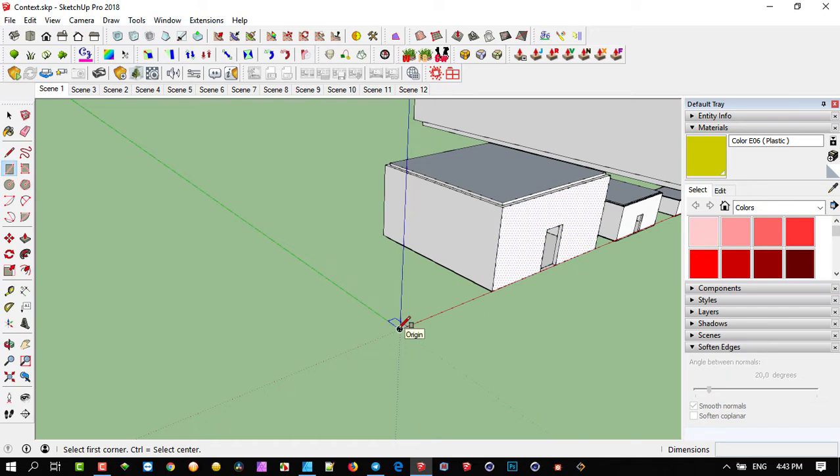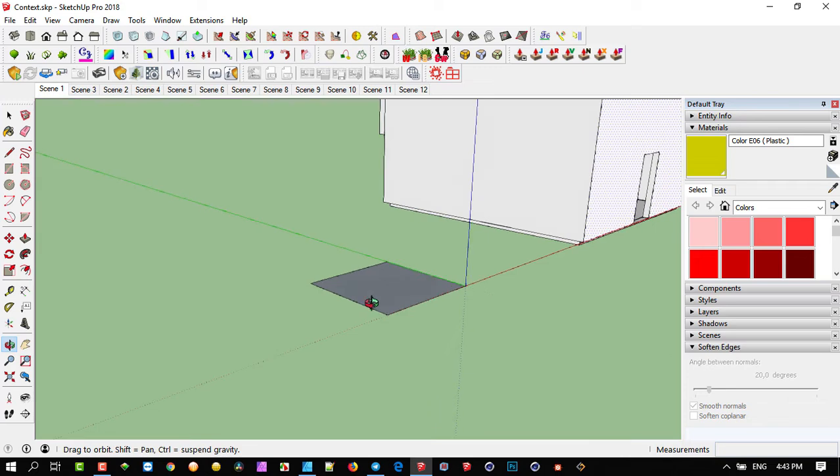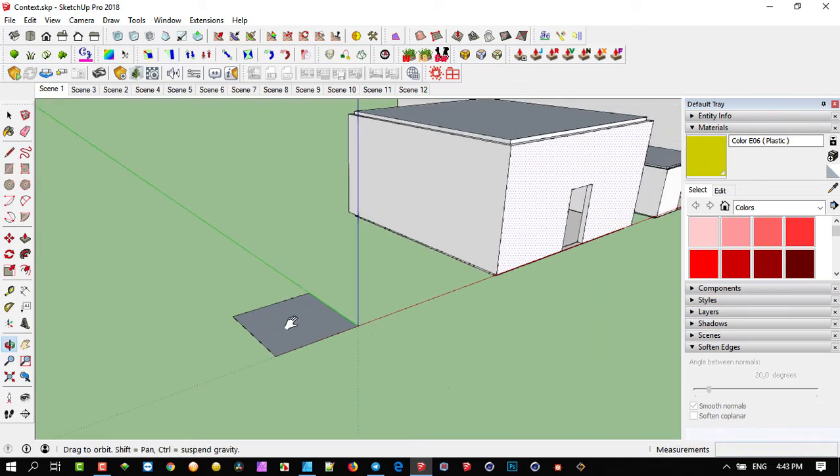measurements. So if I want to draw a room, I'll go there and I'll type in 3 meters by 3 meters. And you can see that in context, that is a 3 by 3 meter area. Because if I drop a light in there and I add an IES profile, the actual profile that manufacturers put into their lights, it will work effectively because it's designed to light up a room of say 9 square meters or a room of 20 square meters.